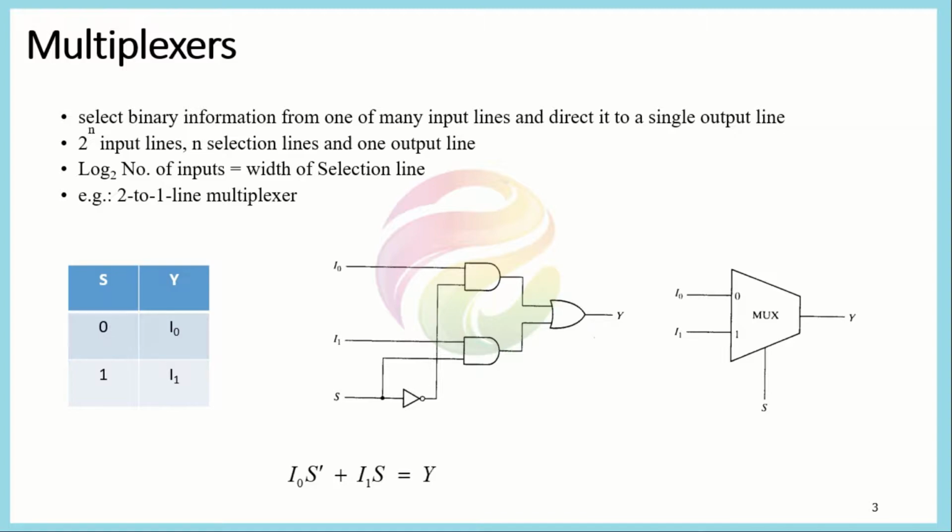For the course of the next two lectures, we will be discussing these basic combinational circuits because these are widely used and a very integral part of any combinational circuit. The first that we are discussing here is the multiplexer. A multiplexer is generally represented by this symbol. A multiplexer is defined as a system which connects a given input to a given output. Generally, we say it is a many-to-one form of representation.